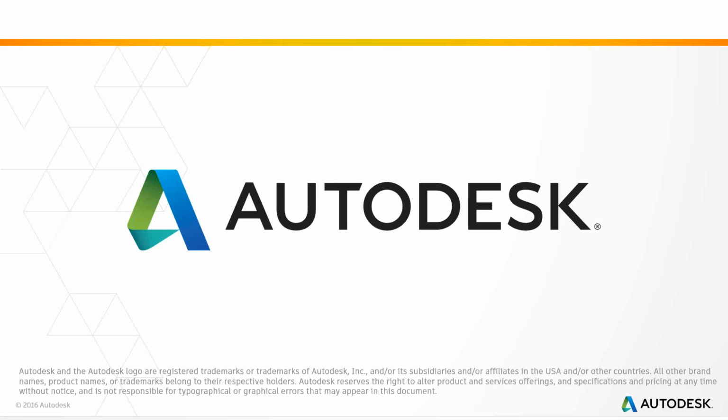Yeah. How about what's new in Moldflow Advisor? So a number of these things actually are also relevant for Advisor. Just top of my head real quick, the ability to create your own toolbars is part of the Advisor workflow. The aggregates, so the isolate cores of warpage with mesh aggregation, is also relevant for the Advisor workflow.